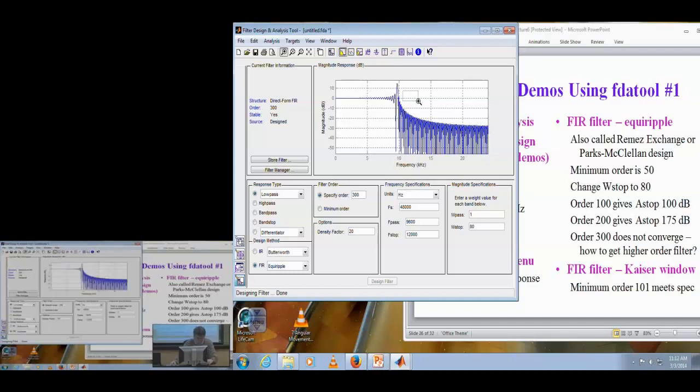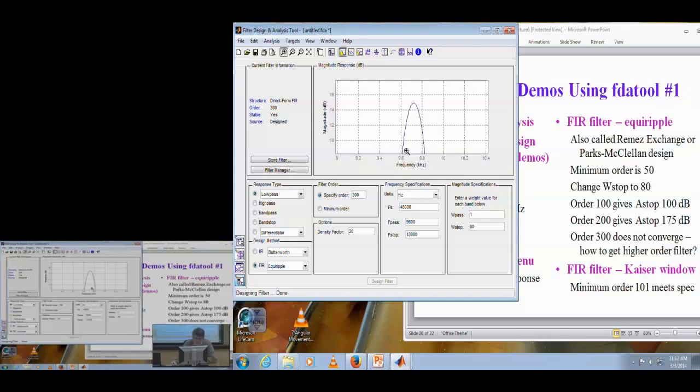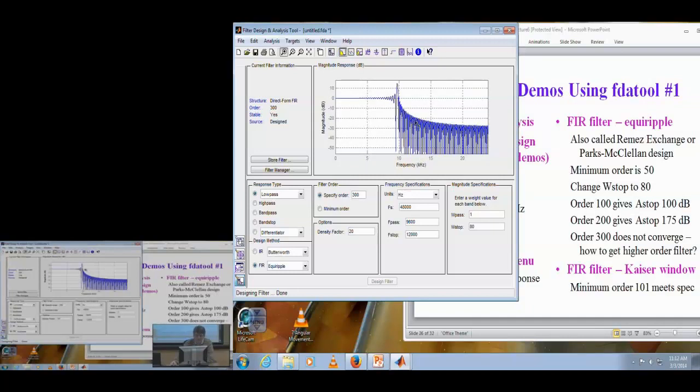There's no input here. We're just designing the coefficients to give us an impulse response. Resonance would mean that there's an input that it's resonating from. Now, if I did input something at wherever this frequency is, so let's call it 9.7 kilohertz, then I would get resonance out. I'd get an unbounded output out. So that isn't much of a filter if you haven't figured that out.